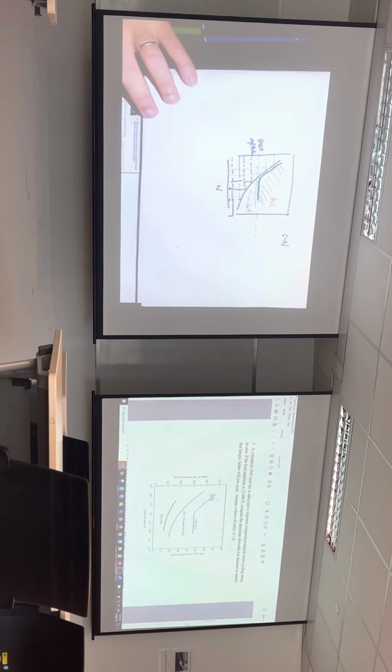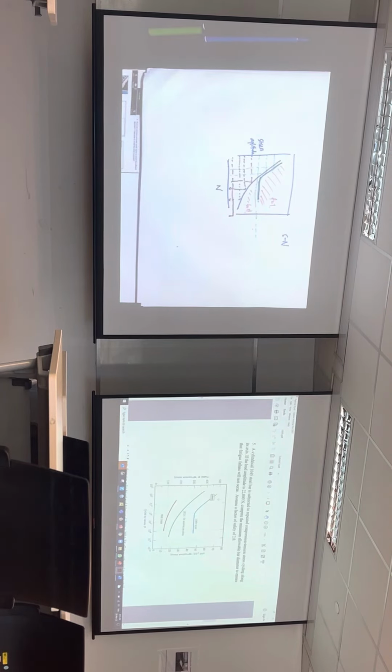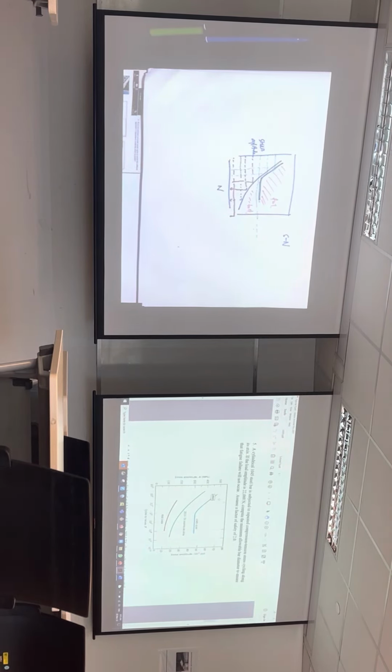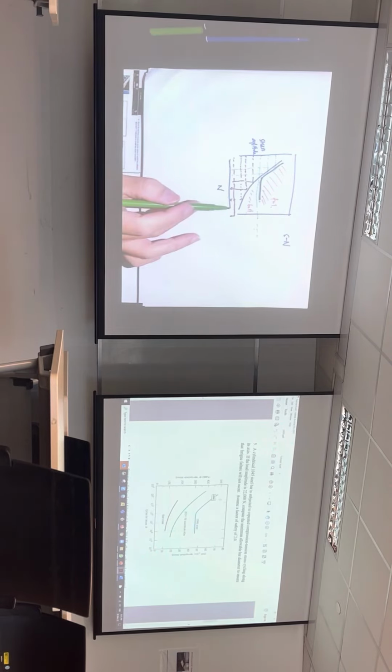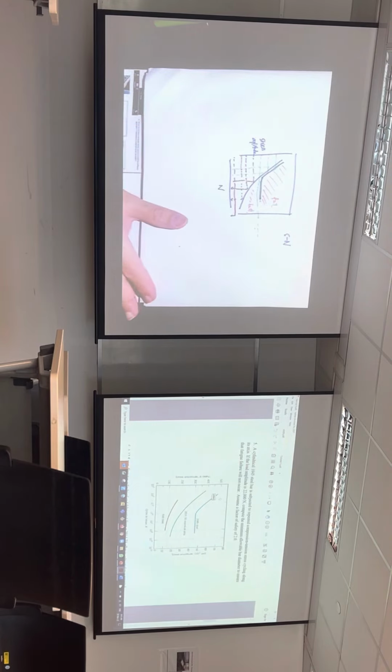So for example, steel. If you want to design something that won't fail by fatigue failure, you design it so that the stress amplitude is lower than this. Then you will never have fatigue failure. This is what it means. In an aircraft where it's aluminum based, no matter how you reduce the stress, you can extend the lifetime, but you will still fail. So this is a material-related issue that you can't get around. Hopefully this is okay. So this is an example.